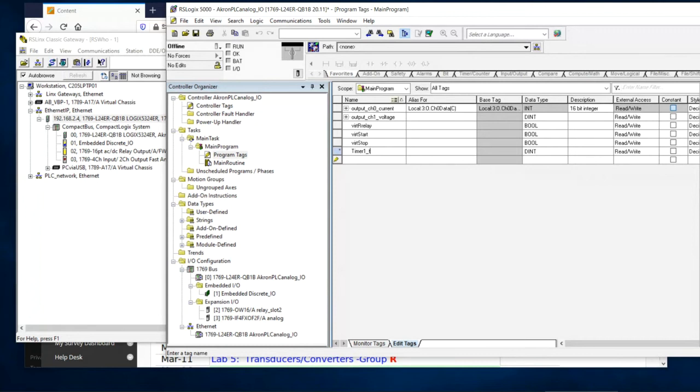It's like tick tock, kind of like a clock, so that I can advance a counter automatically. So I'm going to have timer 1, which again, it's a built-in device, so I don't have any alias for that, but when we come to data type, this is going to be a timer.